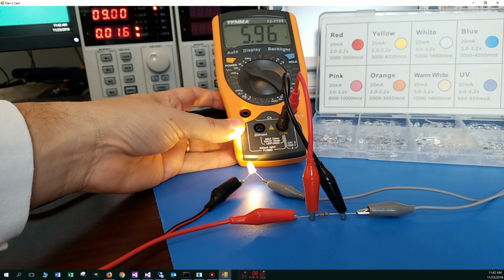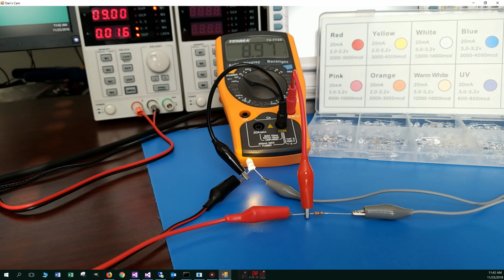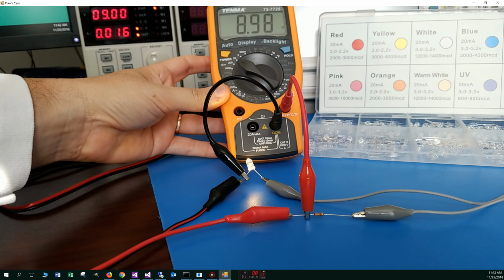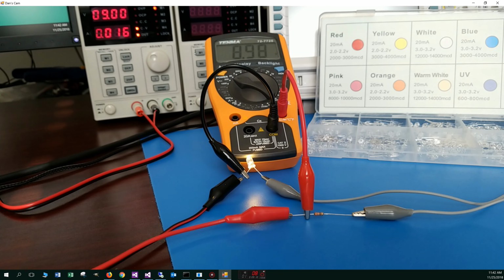Now, if I move the probe over to here, right, we're going to see the 9 volts approximately that's coming across there. It's very close, right? 8.98 volts flowing through the whole entire circuit. All right, so I'm just going to leave it at that for this tutorial, and I'm going to go into a little bit more depth on voltage drop and forward voltage drop and stuff like that in my next tutorial. Anyway, let's just turn that off.